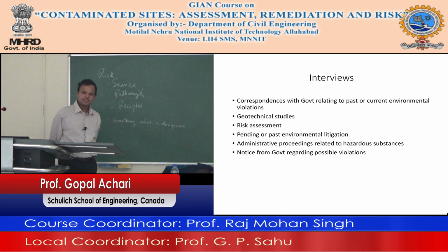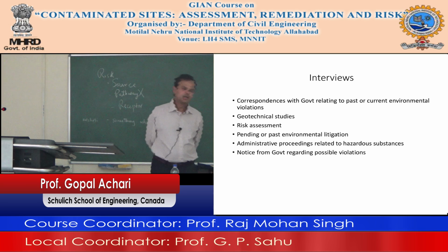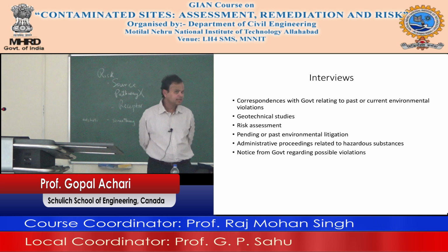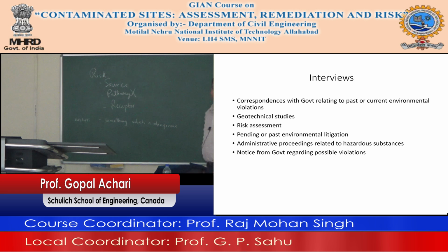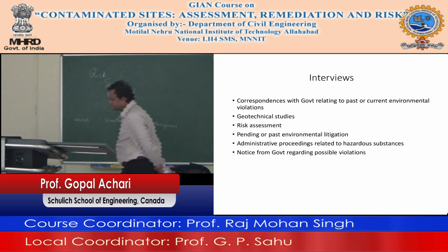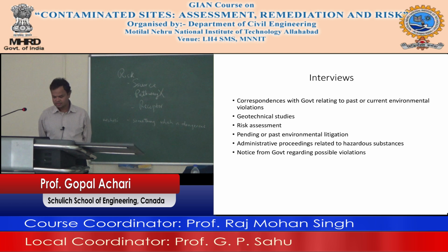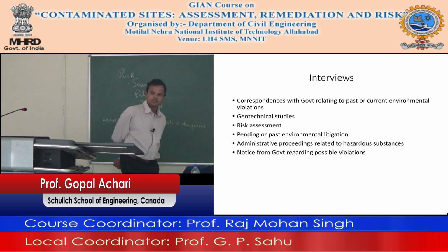Geotechnical studies: if any studies have been done on the site by the current owner, the past owner, or someone else, like what the soil condition is, that will tell you how far the contaminant would have gone. If the soil is sandy and the water table is high, you are looking at some trouble here. If your soil is clay, it may not have gone that far, or the water table is very deep. If somebody has done a risk assessment in the past,